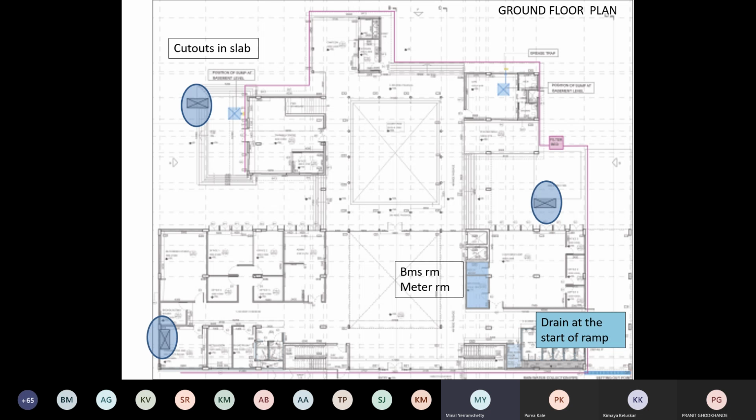Now, where is it getting that outside air from? Because up to the basement, you don't have any. And then somebody asked me, what if it is in the center? Suppose you have it in the center, then you will have to take a duct out from that tiny window. That is the only thing you will have. And from the ground floor, you will have to come up, right? So somewhere you will have to cut and come up.